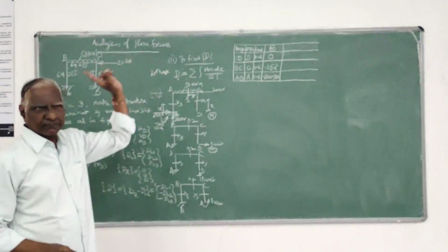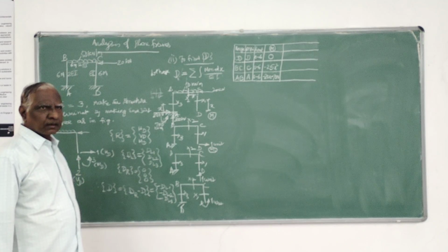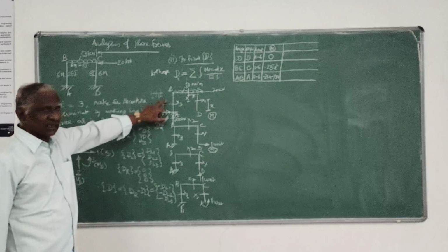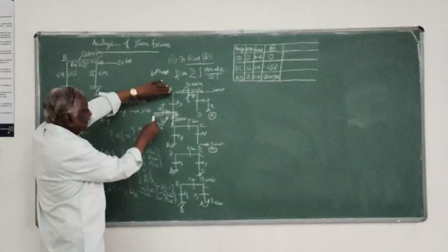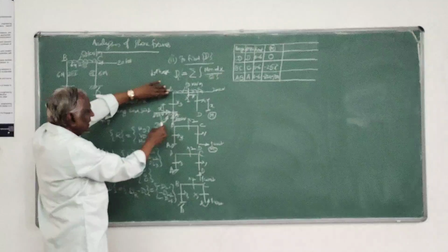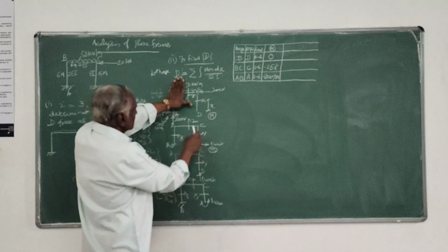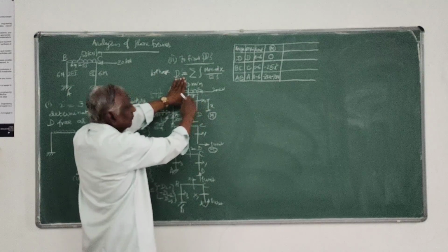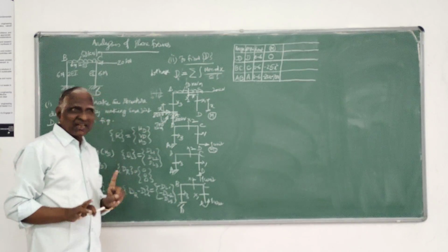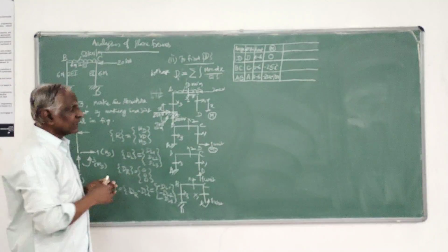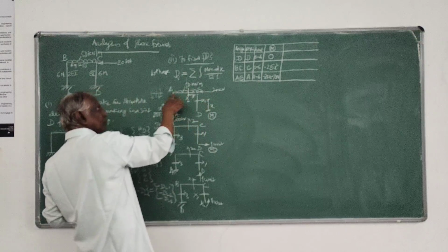That's the moment. We take the moment about the section, not the origin. I have taken the distance x, so 20 into x, and 780. For x2, here no load, only this. About the section, because whatever moment is there holds good from x equals 0 to x equals 6.